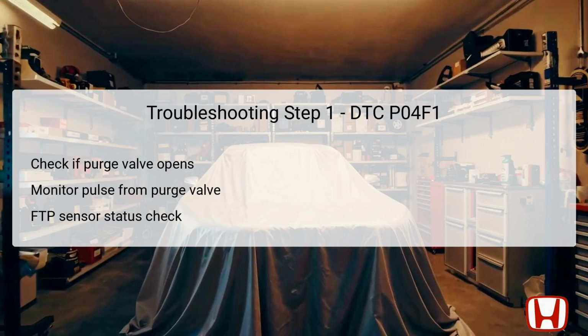If it shows a proper fluctuation during operation, then the system is likely functioning as designed. However, if there is no pulse detected, this may indicate either a failure in the purge flow mechanics or an open state malfunction with the purge valve.